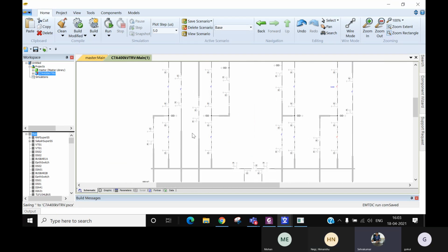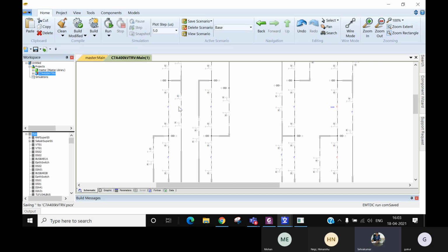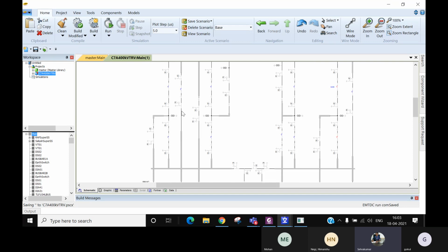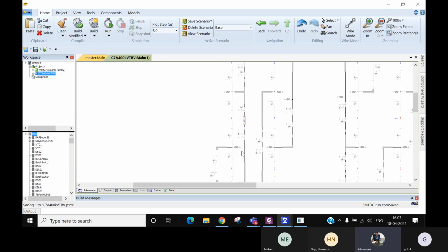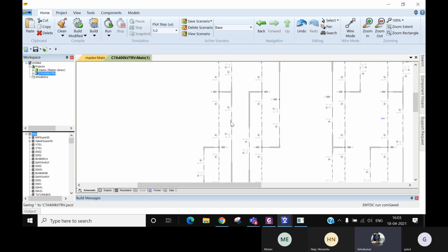Okay. Now what's the point which I'm trying to say? Can you just open this breaker? Go to the reactor breaker. Yeah, that breaker. No need to; you can go back to the main place itself. What I'm trying to say is this breaker starts opening. Correct? Assume that I give a normal open, or there is a fault in the reactor and I'm trying to open this breaker. There is a voltage on the reactor side as well as a voltage on the source side. Correct? So now what is the voltage across this breaker?